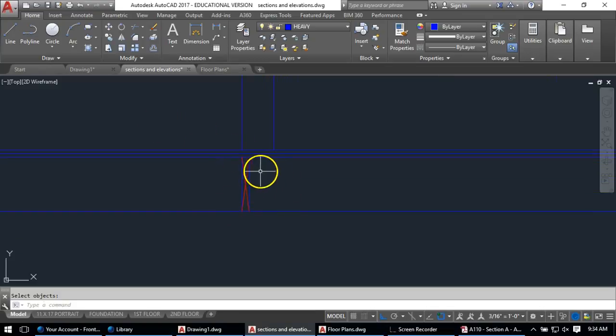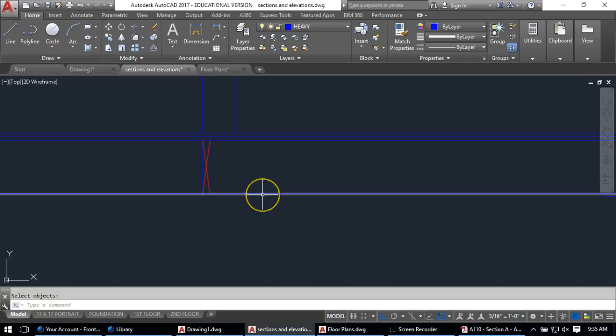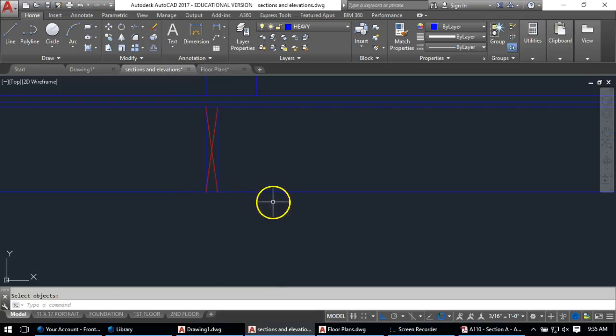I just remembered that. So this piece is cut, and of course the floor pieces, they're cut through as well. But the joist itself, that's running the other way, that's not cut. That's not a cut line, although it is the top of a ceiling line, quite honestly. So I will keep that there. This is the ceiling line there, and then below this I have another little 2 by 4, or I should say it's a 2 by 6.